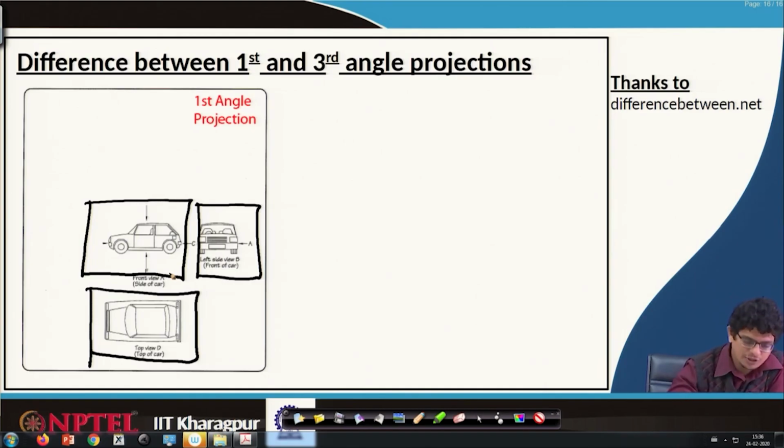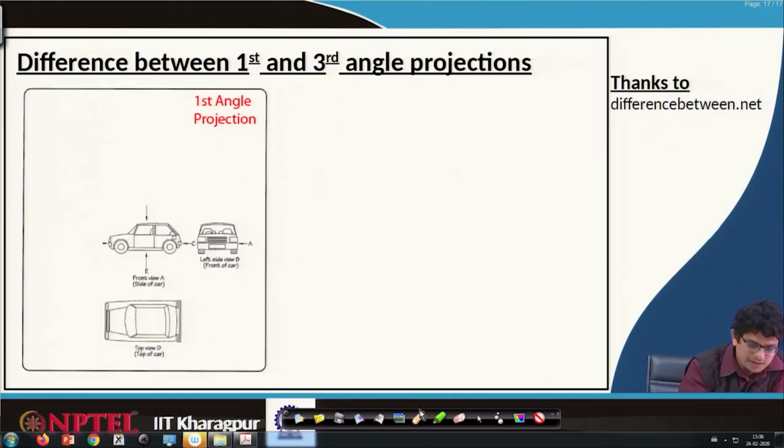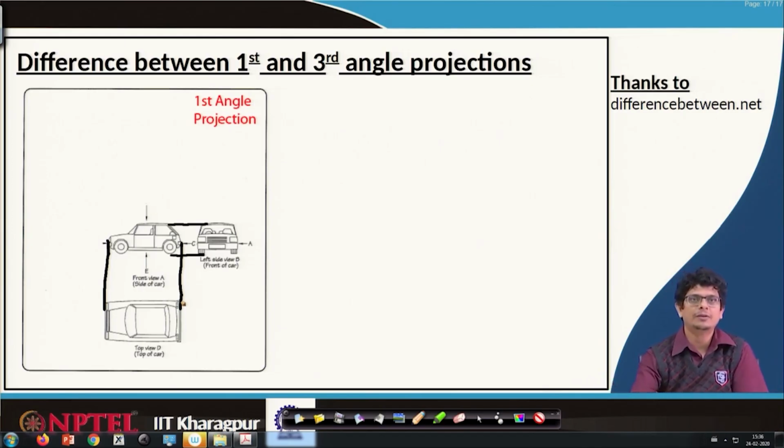The first thing you have to observe is that the front view, top view and left side view make a 90 degree arrangement. The other thing is, if we are joining these lines, they are supposed to coincide; that is projection. So, each point has to be projected onto that. Similarly, the extreme tangent, if we are going to draw it, is supposed to match with this line. Similarly, this extreme tangent is supposed to go at that level. So, your entire view is supposed to be bounded in between these lines.